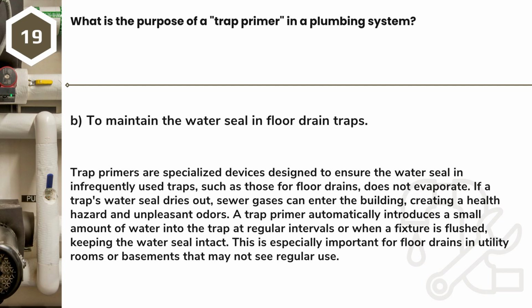Answer: B. To maintain the water seal in floor drain traps. Trap primers are specialized devices designed to ensure the water seal in infrequently used traps, such as those for floor drains, does not evaporate. If a trap's water seal dries out, sewer gases can enter the building, creating a health